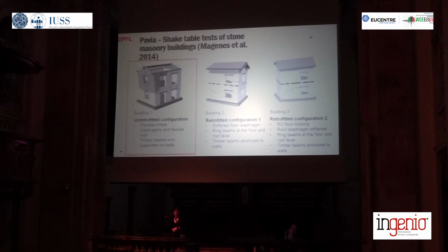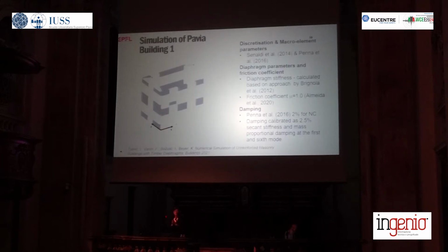This configuration has flexible timber diaphragms and a flexible roof, and also the timber beams are just sitting on the walls. We didn't try to reinvent the modeling. We really just used exactly the model that was developed by Ilaria and Andrea, with the same parameters, the same discretization, of course now with a new macro element.